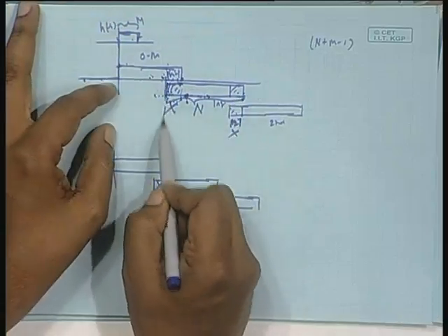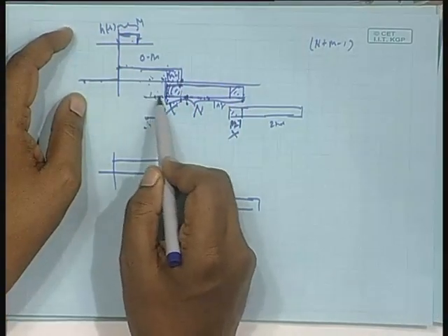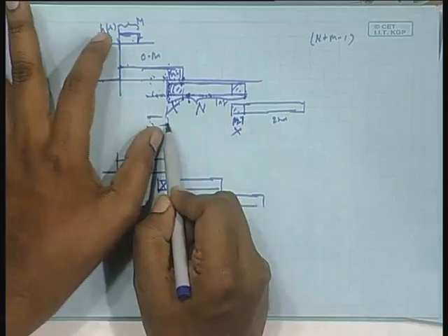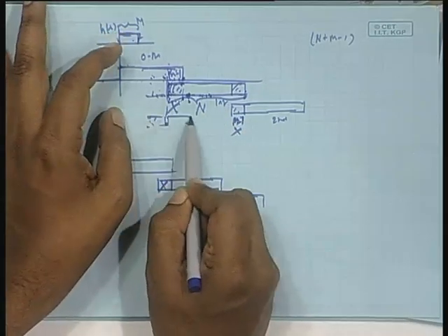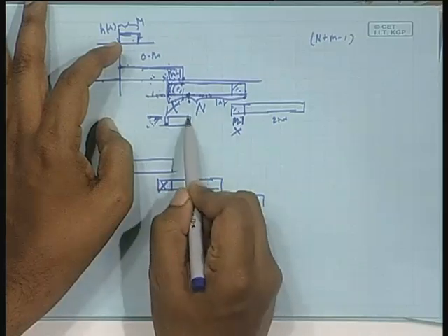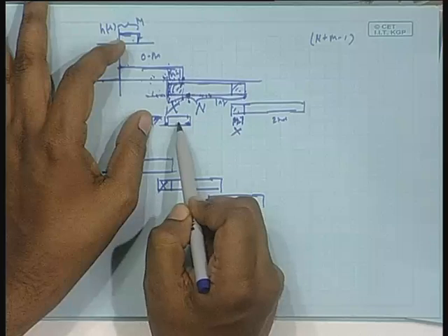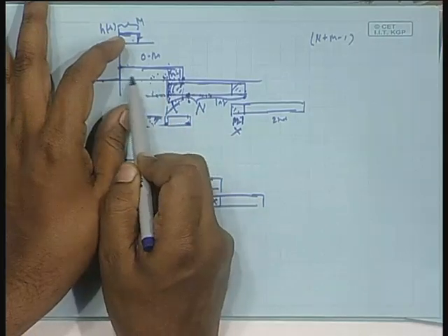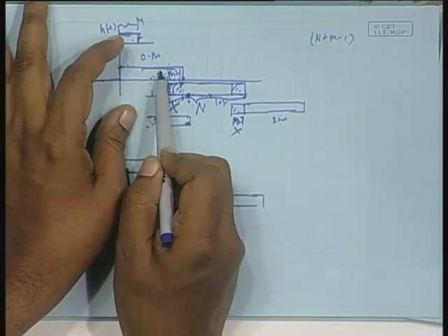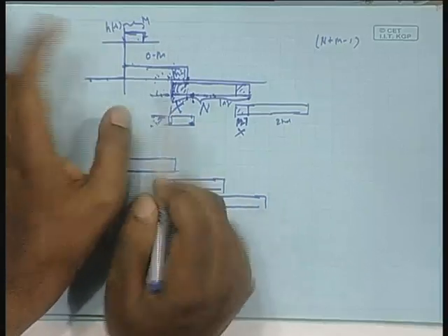Suppose this is the origin, you first reverse it, all zeros are coming, because on this side there are zeros, an incorrect result, but as you move it here, from this point onwards you need purely the linear convolution between this and this. I do not need any data from here. You can say that originally there was some data and now you have got zeros only, so you are getting an incorrect result, but that does not apply here.